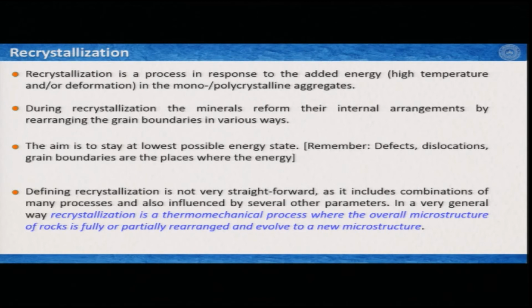Unlike the cataclastic deformation, they are not allowed to produce so-called fractures within the domain of intercrystalline plasticity. So, we will learn how it happens, and the process that takes care of the entire grain rearrangement within the domain of intercrystalline plasticity is known as recrystallization.